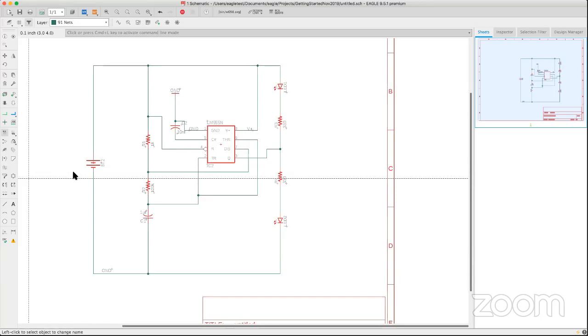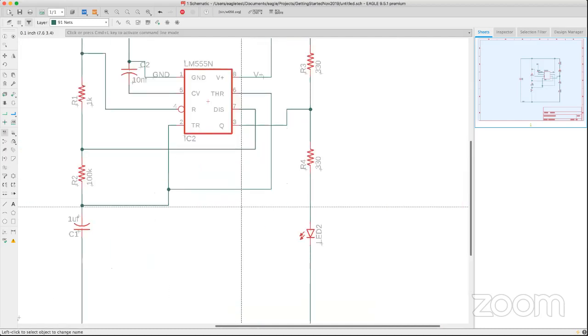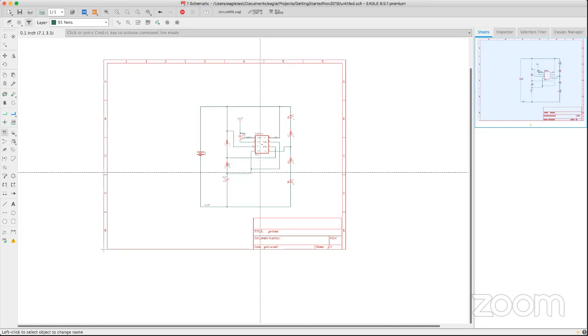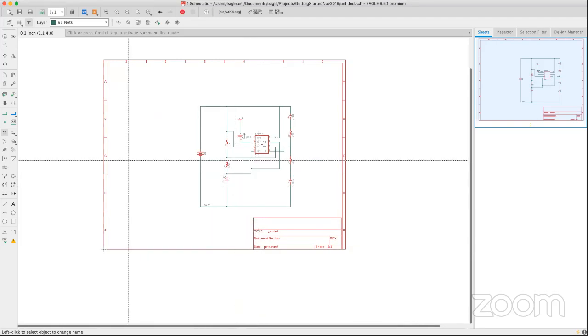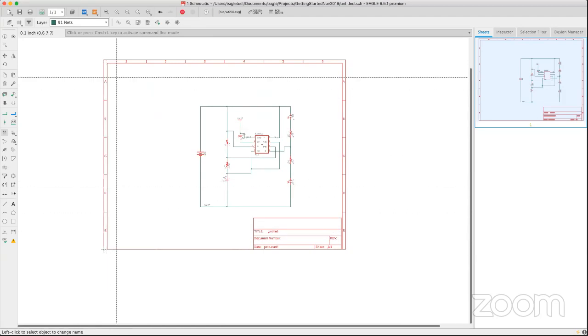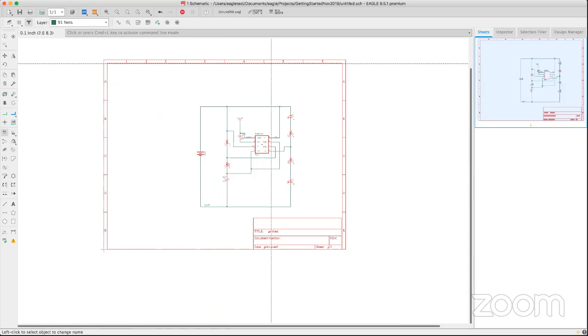Is a frame necessary every time one designs on a schematic? No, it's not necessary, but it's recommended that you do. If you have a schematic with multiple schematic sheets, you notice that the frame has a coordinate system here. As you can see, it goes A, B, C, D, and then 1, 2, 3. And this will grow depending on how many components you have. So as you make the frame larger, it'll make it larger.